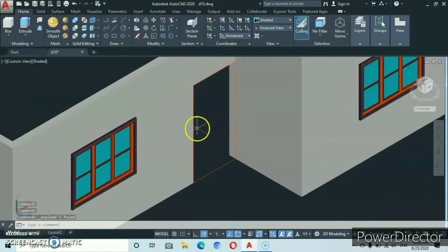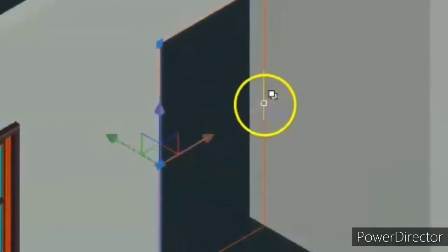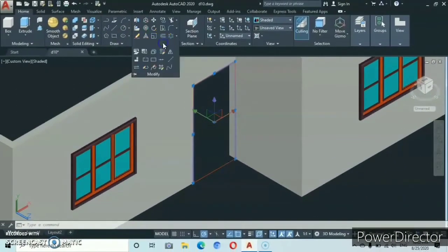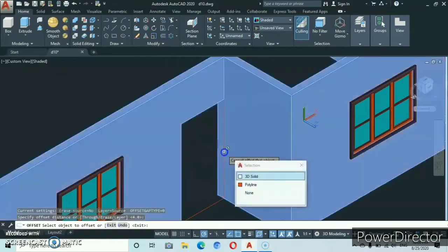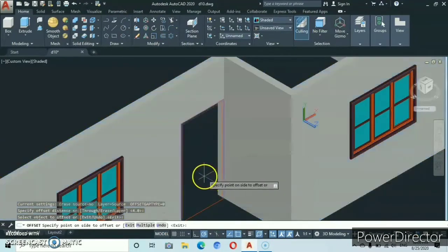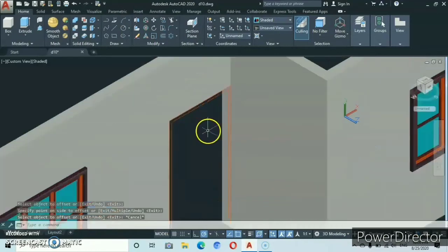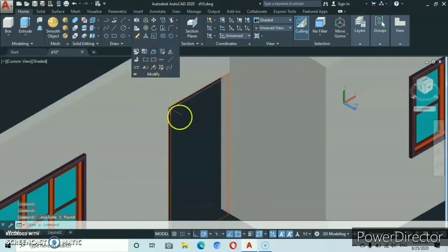Then let's carefully join these other three lines. Select this other line, then this one. Then we go to join these lines. Let's now go to offset, to type in an offset this time of 4. Enter. We select this polyline, offset it inward, then escape. From here, let's select this inner polyline, and explode. Go under modify, explode.